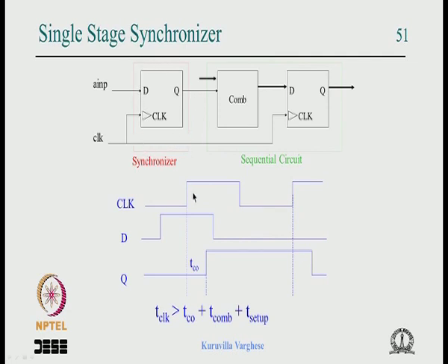Okay. Now if you look at the clock waveform, a clock comes and whatever is the analog input here, if it is like this, then it appears here with a delay of TCO every time. Even if it changes before, upon the clock edge only it changes the state, and you know that now it has become synchronous because every time after the clock it appears neatly with a delay.